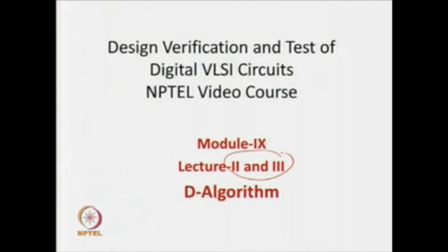But in these 2 lectures we will have a very detailed look at it, that is, we will go for a very formal way of defining the algorithm, because the D algorithm, as we will see, is the backbone of digital testing. Next we will see sequential circuits and several BIST architectures, but for all of them the D algorithm is the backbone. From the D algorithm there were other advanced versions like PODEM and FAN, but the basic backbone which we should learn in detail is the D algorithm, because it was the starting point for all sensitize, propagate and justify based ATPG algorithms, which still occupy a prominent role in digital testing.